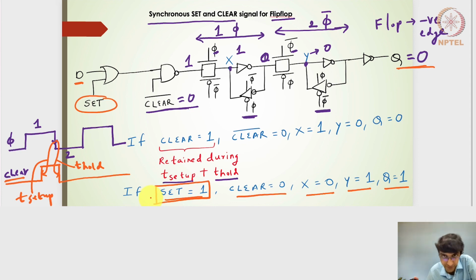Right, one more piece of information here is, if you notice, in the latches or the flip-flop designs, we used to have an inverter here instead of the 2 input NAND gate. And our t setup time used to be, if I really want to characterize the t setup time for a particular latch or flip-flop, this particular inverter delay followed by the transmission gate delay and followed by this particular inverter delay.